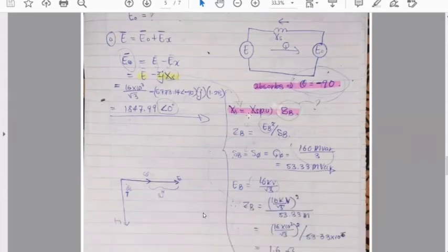That's exactly what we have to do here. It's given to us in per unit, so you have to multiply it by the base impedance. All right. So remember, don't forget what our goal is. Our goal is to get this value here. In order to get that value, we are using this equation. We have to calculate everything that is in this equation. I believe the only thing that is given to us is the E. And of course, you have to put it in per phase. That's why it's divided by the square root of 3. Everything else you have to calculate.